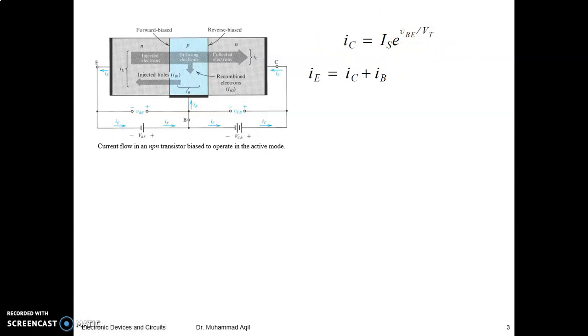We started from here when we were studying the NPN transistor, but later when we did the small signal modeling and characteristic curves, we saw that the collector current is not constant for a given VBE if you increase VCE, right? So that was called the early effect. We did it, right? Similarly here, because we are introducing the PNP, currently we are taking the collector current as depending only on VBE. It has a small dependency on VCE, neglected at this time. So it means we are neglecting the early effect.